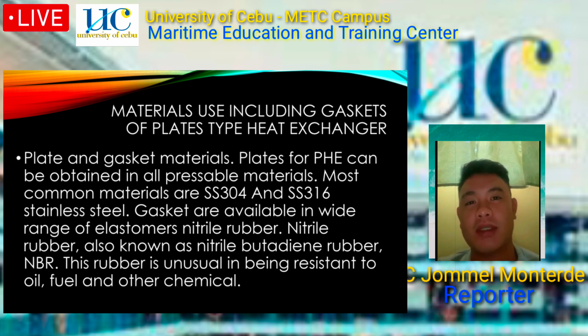Plate and gasket materials. Plates for PHE can be obtained in all pressable materials. The most common materials are SS304 and SS316 stainless steel. Gaskets are available in a wide range of elastomers, such as nitrile rubber, also known as nitrile butadiene rubber, NBR. This rubber is unusual in being resistant to oil, fuel, and other chemicals.